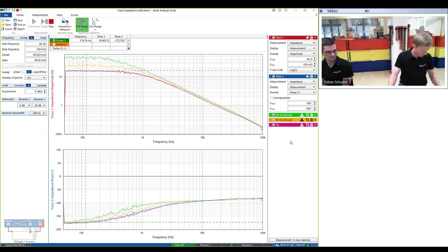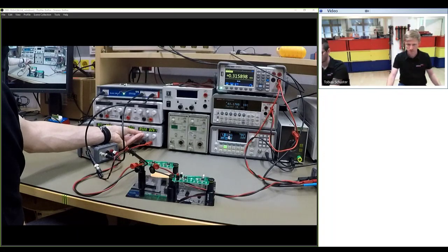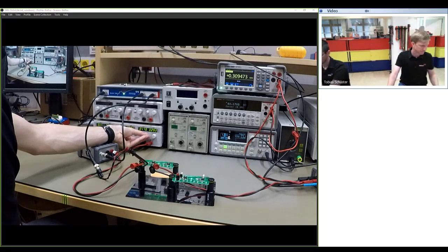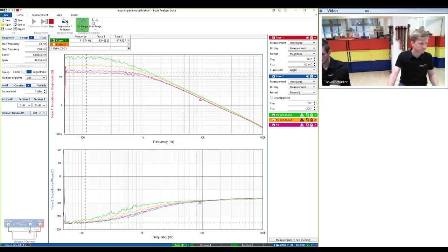So what's the minimum we can go? I think you can go to 4 volts in addition. Please try slowly. Lower the input voltage a little bit. I think that's too low. It was too low. We have a 0.6 volt drop in the line injector, so you will be able to go to 4.6 or 4.65, something like that. Some 4.7. 4.65.